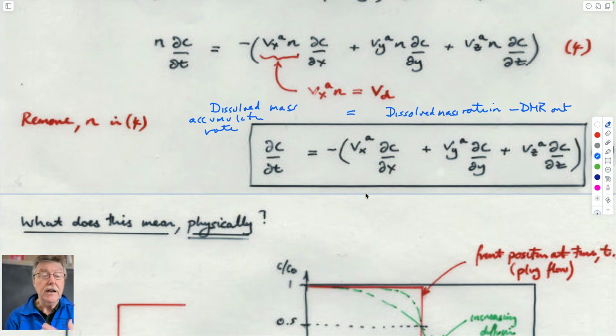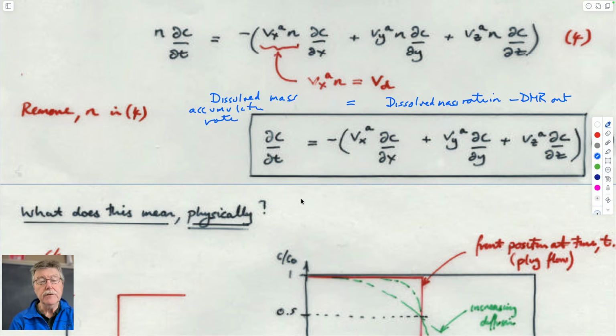So I don't care so much about this. So we have a couple of partial differential equations. We can combine them. And we will typically write this expression as I'm going to write here. I think I've got enough space to do it. And that is the accumulation of dissolved mass is equal to, so this equation is a first order partial differential equation. It represents moving it along with the velocity of the water. This is the advective velocity.